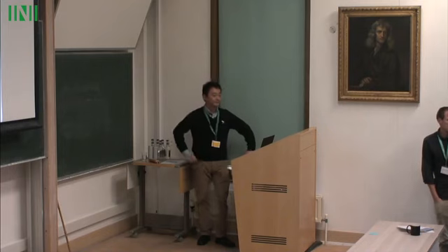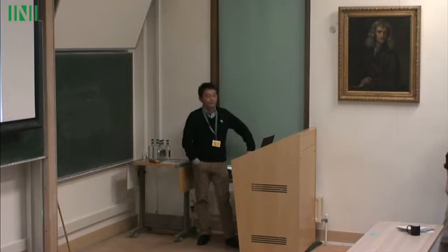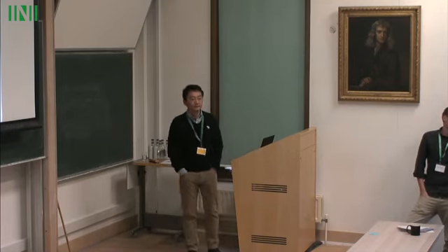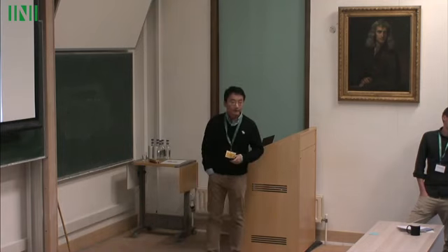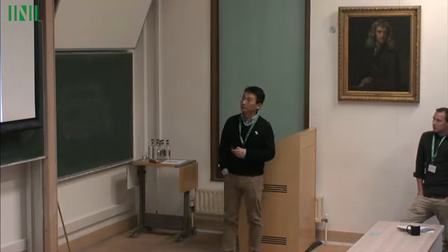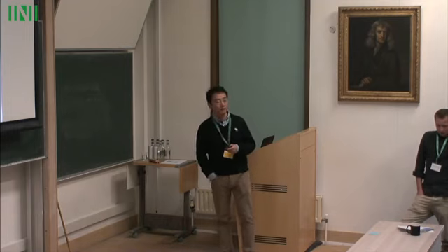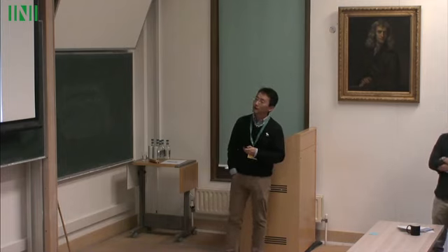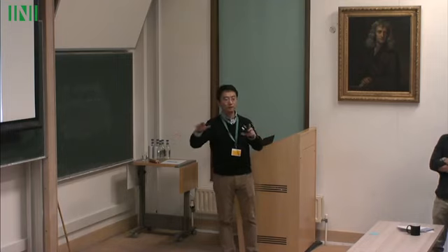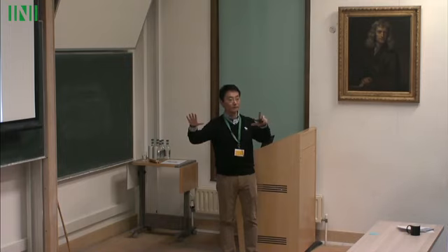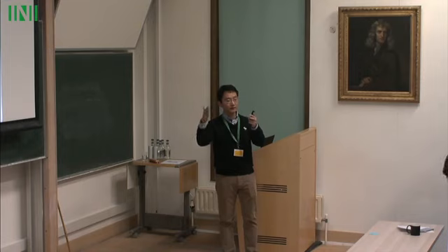Any questions for Andy? I was interested in the ACOPF partitionings of the graph. What would happen if you just chose random partitions and took statistics of that? That's a good question. So we're still experimenting on that and trying to figure out a principled way to do it. So in the beginning we thought, okay, if you partition, say, into two subsystems, maybe you want to partition into two subsystems with equal number of nodes and minimize the number of tie lines. So then you minimize the duplicated number of variables.